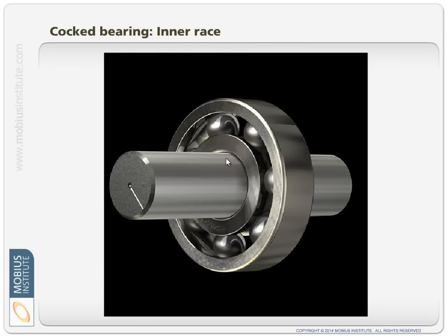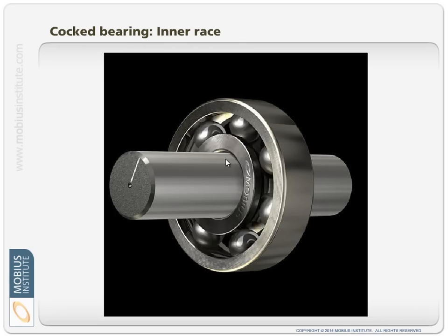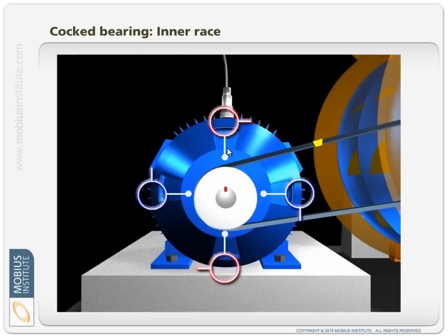And oh look, the bearing isn't mounted correctly on the shaft. It's rocking and rolling every time the shaft turns, which is damaging our bearings. But if we compare the phase from here to here to here to here, we see a 90 degrees phase shift because of that rocking motion. Now, yes, we wouldn't take a reading here because we've got a belt. I need to come up with a better illustration, but anyway, that's what we've got.